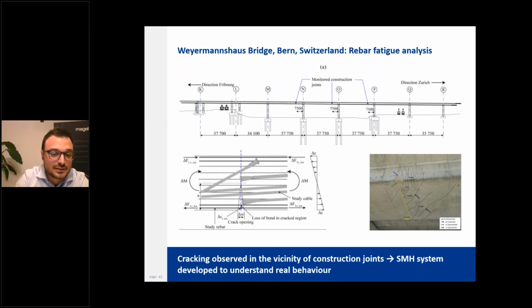The engineers could not know exactly when and why this cracking had begun, but obviously concerns about the structural safety were raised. So more detailed studies started, and it seems it was a combination of factors like shrinkage, increased traffic loads, or also as a result of the staged concrete casting and pre-stressing process.